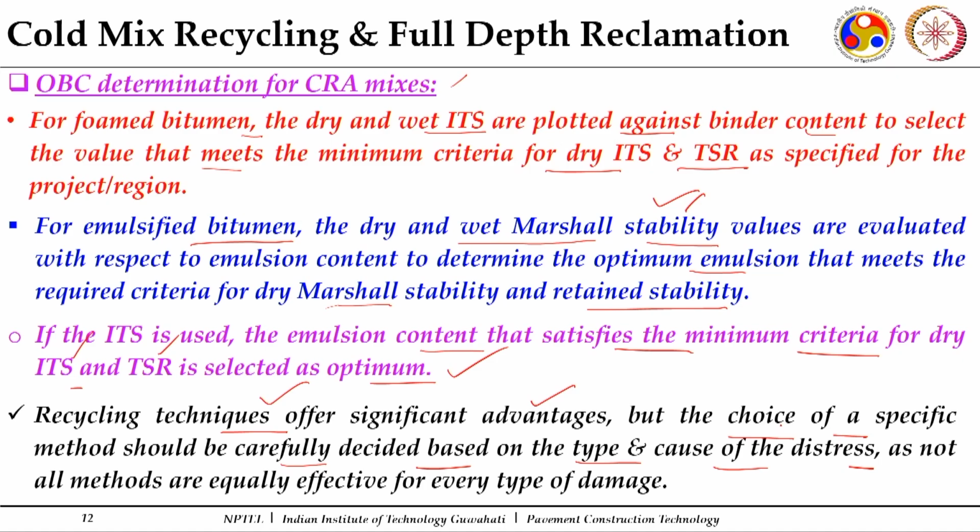So, in these recycling techniques, it is very important to choose the correct technique to be used for any particular type of distress. For that we need to know the causes of the distress and which particular layer is contributing to it, as not all methods are equally effective for every distress. If the problem is only with your surface or wearing courses, and you attempt a full depth reclamation, again it is a waste of money.